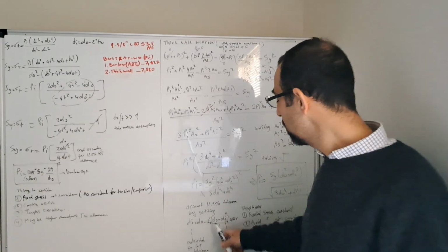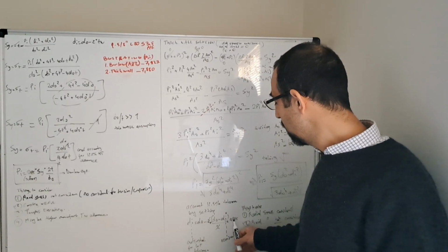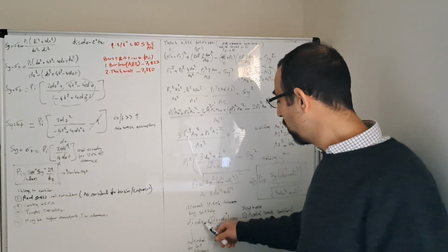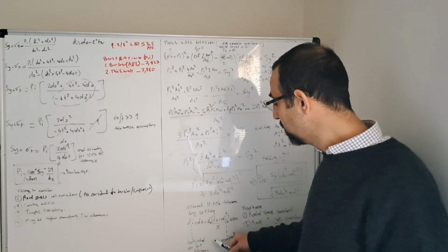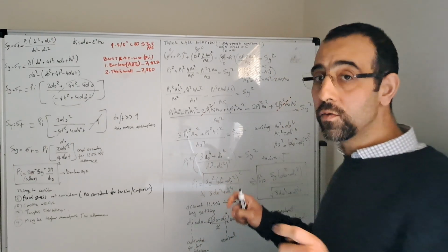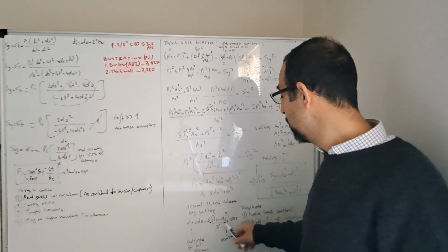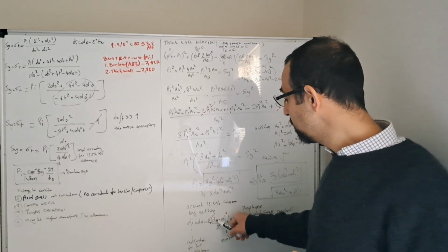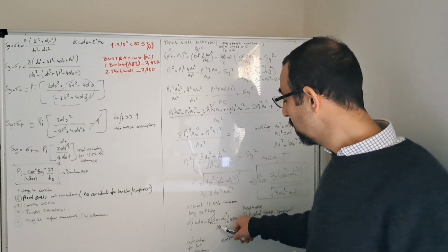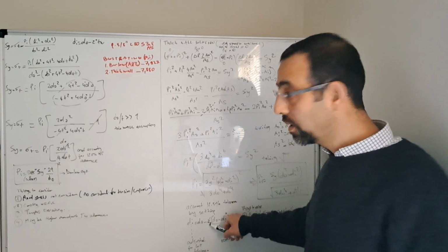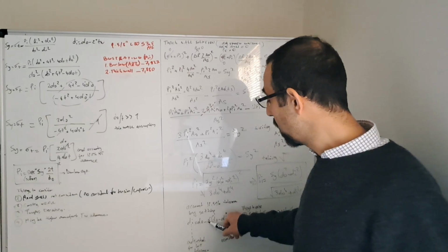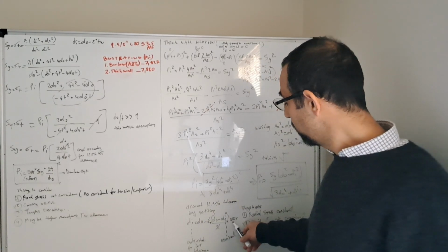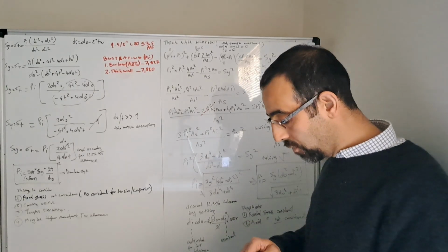So if you need to compare apples to apples, what you need to do is modify the inner diameter to account for the wall thickness. How do we do that? We need to account for the 87.5% here. Therefore the new inner diameter, when accounting for the wall thickness, will be the inner diameter equal to the outer diameter minus the original wall thickness divided by 2, but we again multiply by 2 to get the inner diameter, so those two will cancel, times the allowance.